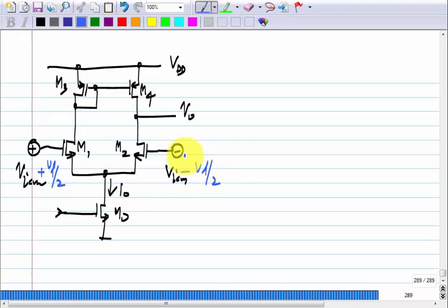Okay. So, now, let us say V naught becomes very small. Okay, because if you apply a negative VD, V naught will fall. If you apply a positive VD, V naught will rise. So, let us say you applied a small negative VD and V naught keeps falling. Okay. At what point will any transistor get out of the desired region? M2? Okay. So, again